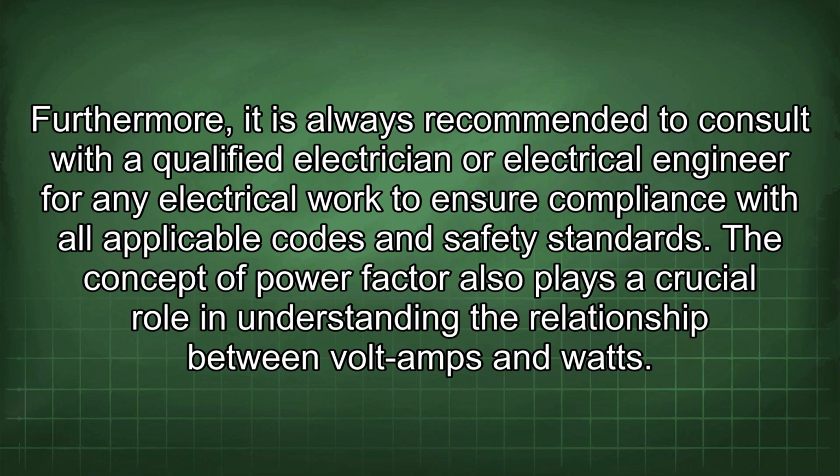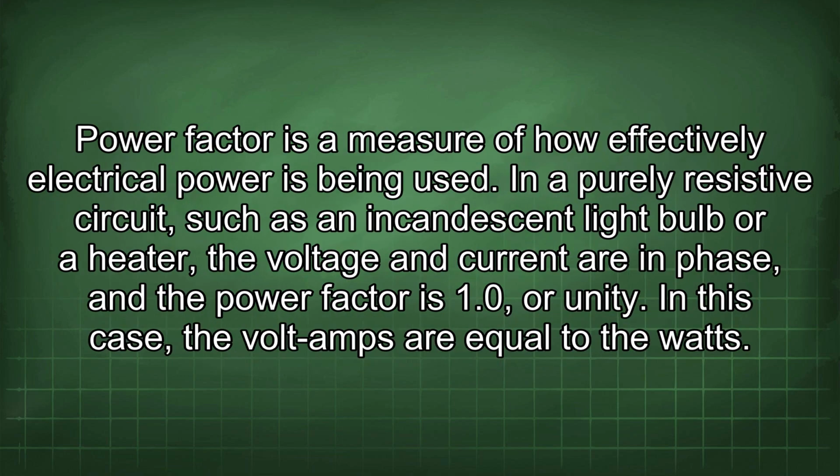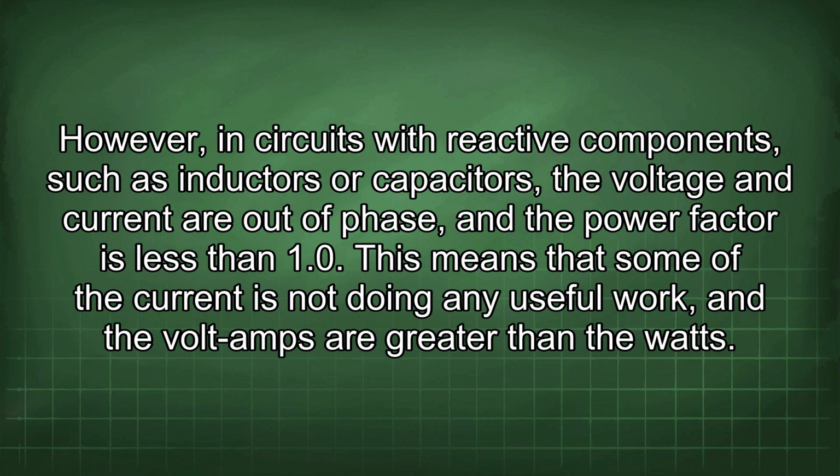The concept of power factor also plays a crucial role in understanding the relationship between volt-amps and watts. Power factor is a measure of how effectively electrical power is being used. In a purely resistive circuit, such as an incandescent light bulb or a heater, the voltage and current are in phase, and the power factor is 1.0, or unity. In this case, the volt-amps are equal to the watts. However, in circuits with reactive components, such as inductors or capacitors, the voltage and current are out of phase and the power factor is less than 1.0.